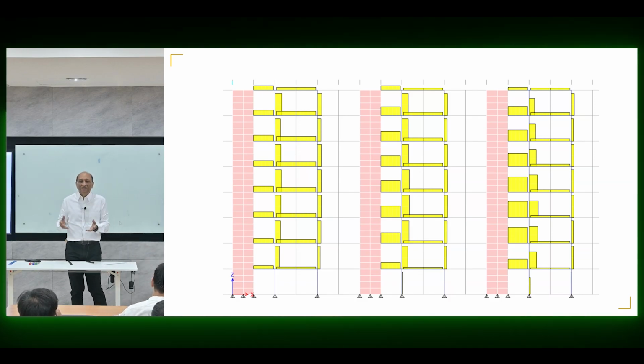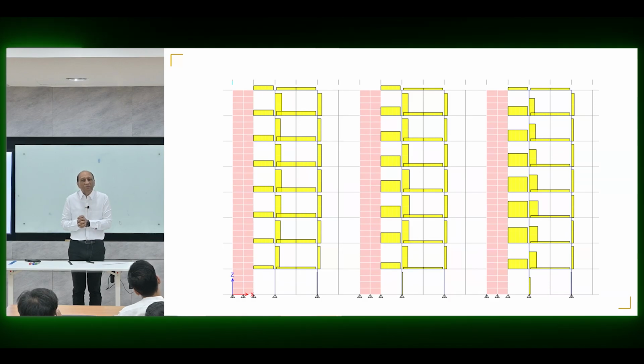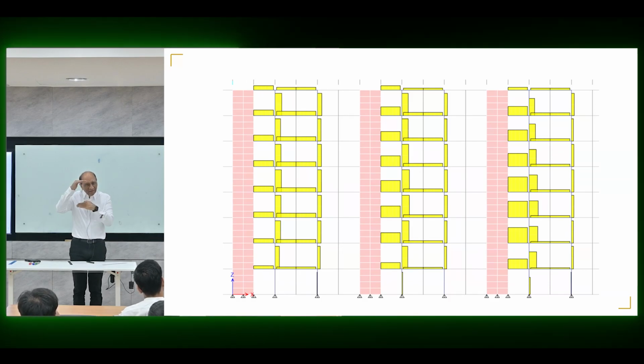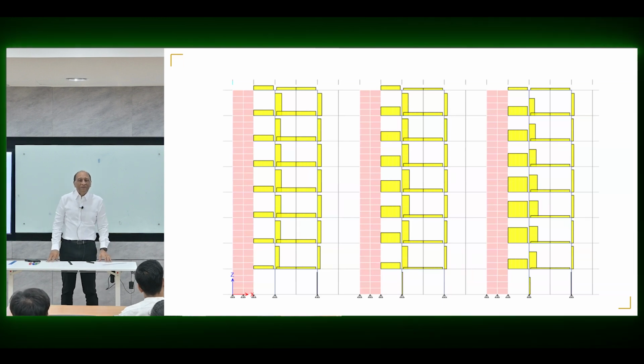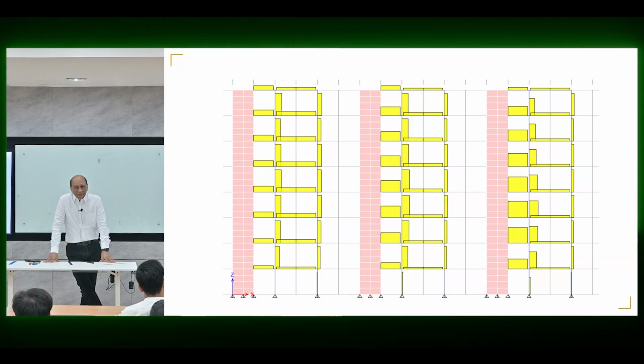This shear is generated because of the bending moment produced, which means control the bending moment produced, right? That means limit the reinforcement in the coupling beam to the max, calculating it backwards from the shear capacity. So the shear will never exceed the capacity of the beam. You control it by controlling the bending capacity. That's the principle of the capacity-based design.